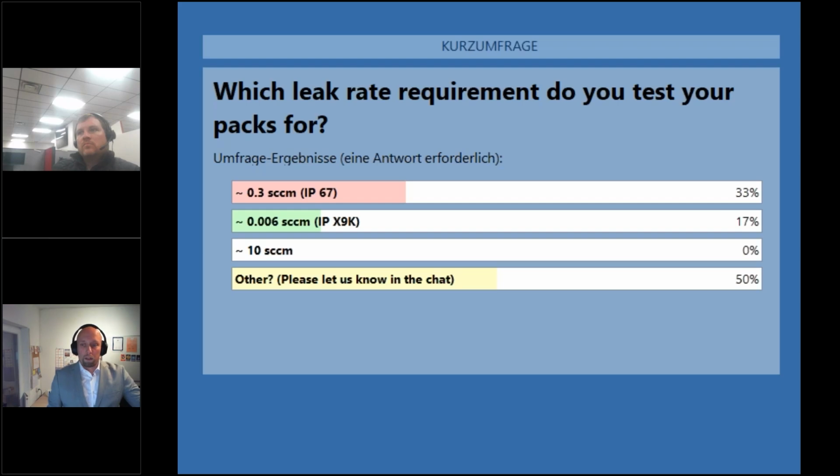You can do laboratory testing where you utilize an application lab from production specialists. You can try to reduce the cycle time by different means, let's say free volume decrease, optimization of the surfaces, correct pumping system dimensions or sizing of the suction speed. In the end, this all contributes to cost savings, as initial costs or running costs are always to be considered in a high production environment like this in the battery world.